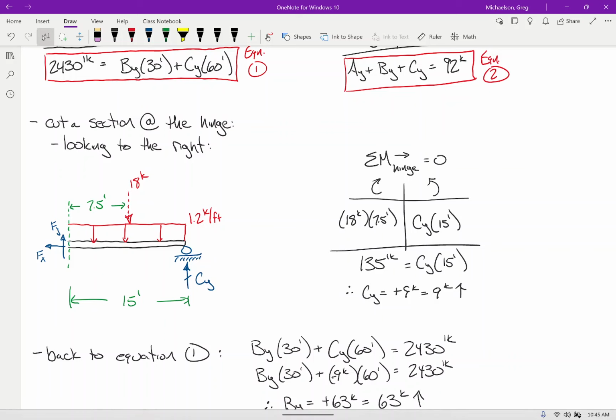But we never really use the ones that move, right? Not really, but we do have connections that are designed not to resist moments, like simple shear connections and things like that. Do we actually physically build hinges in structures? Not so much, but we do design connections where we assume they act that way because we assume they don't have any moment strength. Connections are where structures get really expensive. If you don't need a connection that resists moment, you won't put one in there because that's more bolts, more plates, more hole drilling, more time on the site, more money.